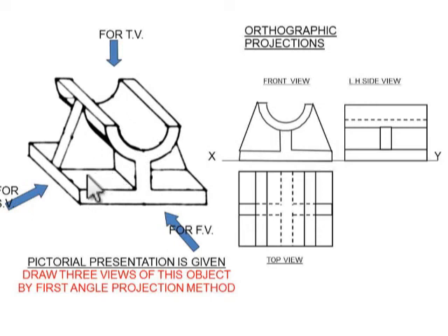So for drawing hidden edges, we are representing the hidden edges using dashed lines. And again there is an edge over here, a vertical edge from here, and it runs up to the next end. If I'm seeing directly from the top, this portion will hide that edge. So to show that one, you are drawing those edges as hidden lines.